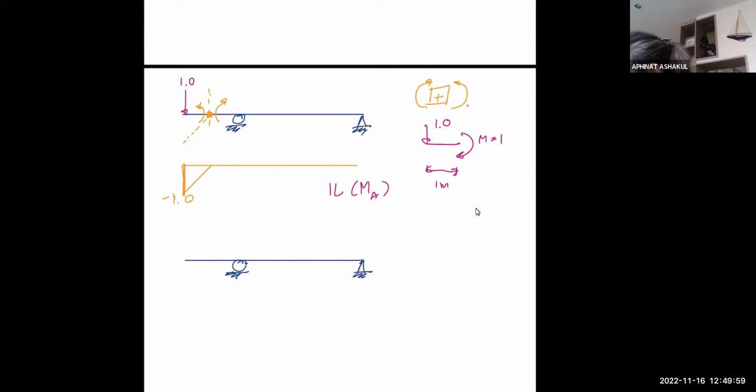Point B is the support itself, right? Here we go again with the support. Now we just add the hinge here at the support. And the positive moment is in this direction, right? To the right is counterclockwise, to the left is clockwise. So again, when you have the hinge there, this guy is free to come down.